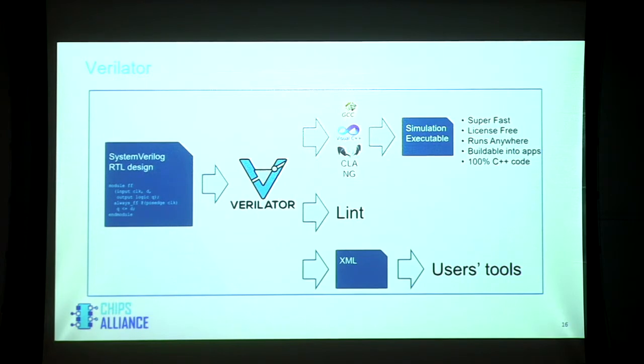Verilator is, if you are in the ASIC business and you haven't heard of Verilator, check Verilator out. It's a 20-year-long project started by Wilson Snyder. True genius. He started this out of kind of excitement, and it has grown into a serious tool. And I use it in my team. Many of the companies I interact with, I discovered they use it. It's really super fast. So if you want to break the record in your RTL simulation speed, this is the way to go. And it uses multi-threads really well, etc.